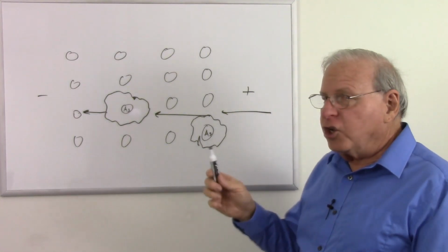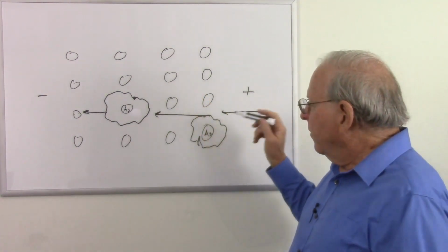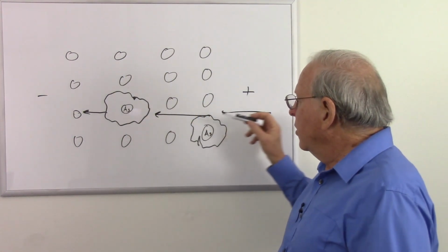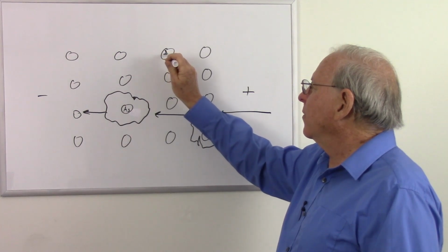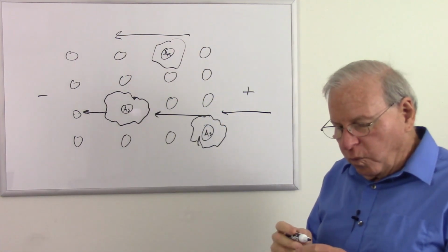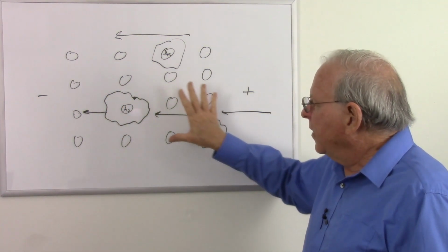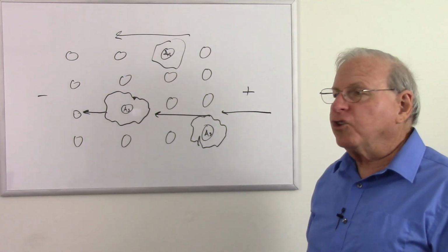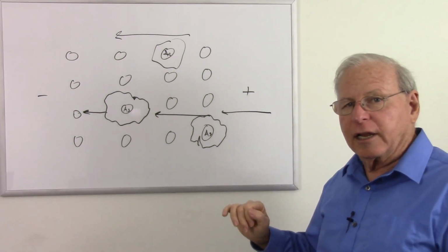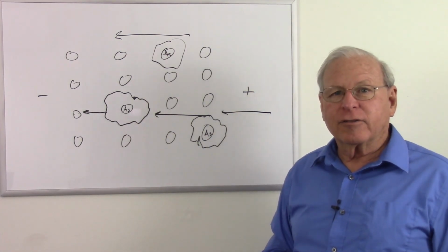So when we dope this with impurities, in this case arsenic, we now, let's go throw another one up here, we can get those to flow. So when we dope it with these materials that have an extra electron, we call those donor materials because they donate an electron to the crystal structure. We now have something that conducts.